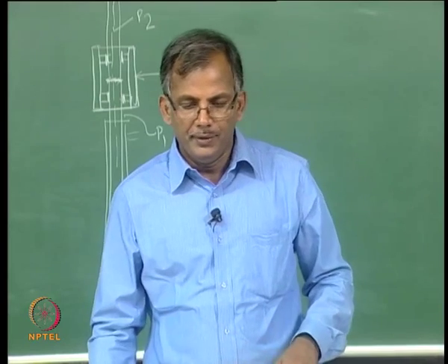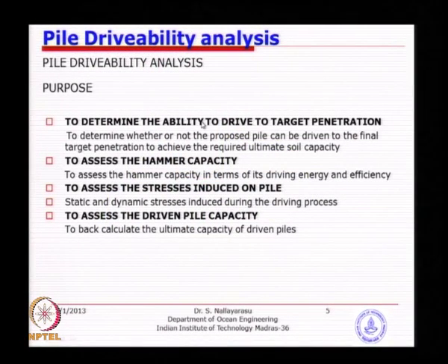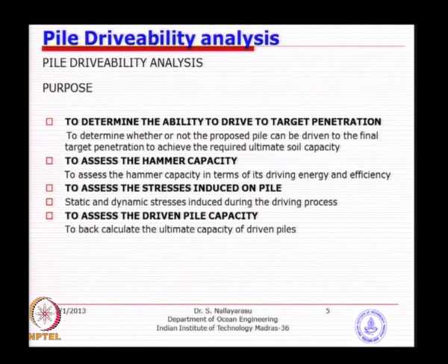So, that is why we have to rely highly on the theoretical capacity predicted by you based on the engineering properties of the soil, and that is the end. That means our design has to achieve the penetration that you have decided, and the pile has to reach there at least that much, and that is the only surety that we conclude the pile has sufficient capacity. So, we have to make sure that the system that we derive and take offshore has sufficient capacity and energy that the pile can be driven to the target.